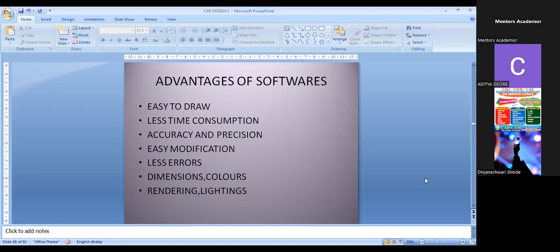Dimensions, in CATIA software, in the drafting workbench, we apply the dimensions, diameter, radius. Next one is aligned dimensions. Next one is linear dimensions. Next one is angular dimensions. Different types of options are available in the drafting workbench. Because of this, the final product you forward to the production department with specific dimensions and with specific GD&T concepts. Everything is mentioned by using the drafting workbench.